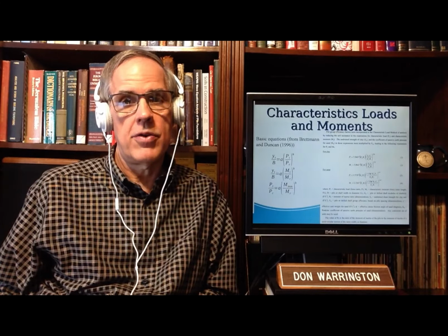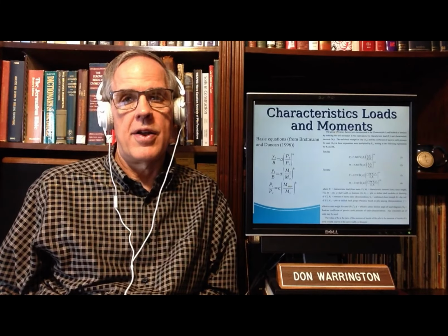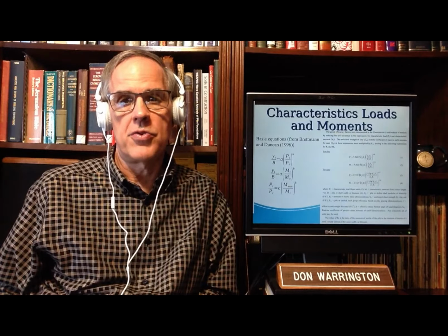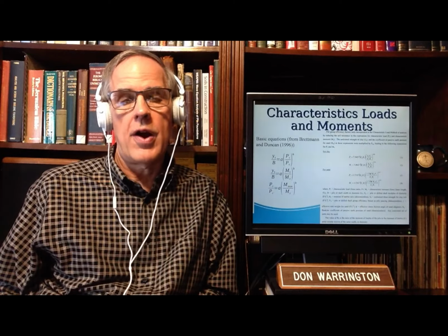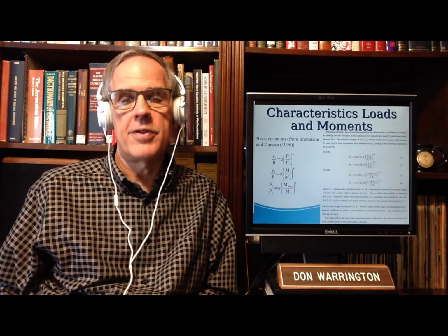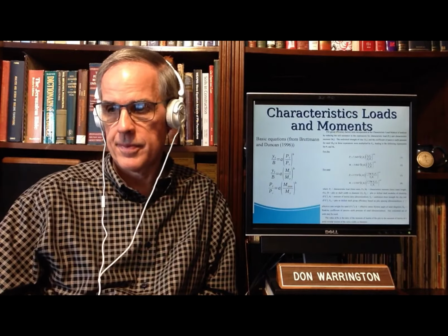Now, mind you, the characteristic load and the characteristic moment are not the real moments in the pile. In fact, they're several orders of magnitude greater than that. What they are, however, is expressions of the response of them. How much moment would you get if you apply certain loads to the pile?